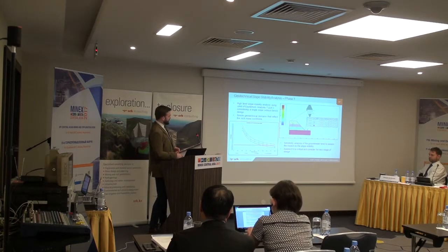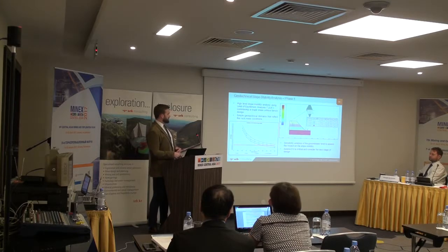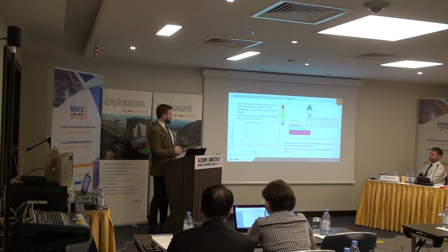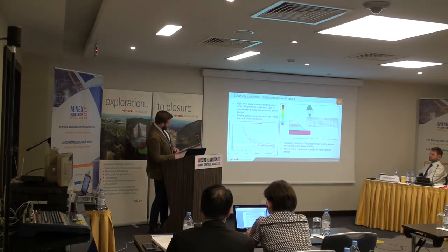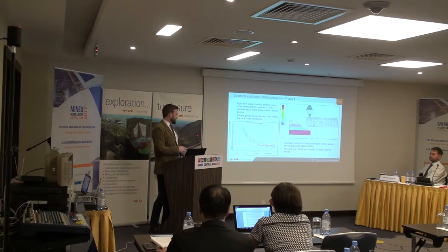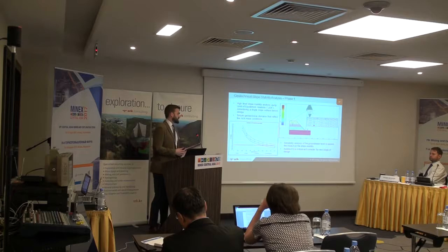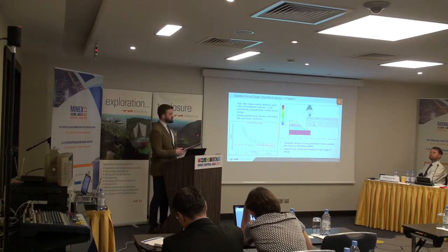And what we're trying to do is a sensitivity analysis and work out the impacts of it being dry, partially saturated or wet. Although it's not very clear on this diagram, it's just trying to show the different factors of safety for the limit of equilibrium analysis to see the impact, and if the groundwater is critical on the pit slope design.